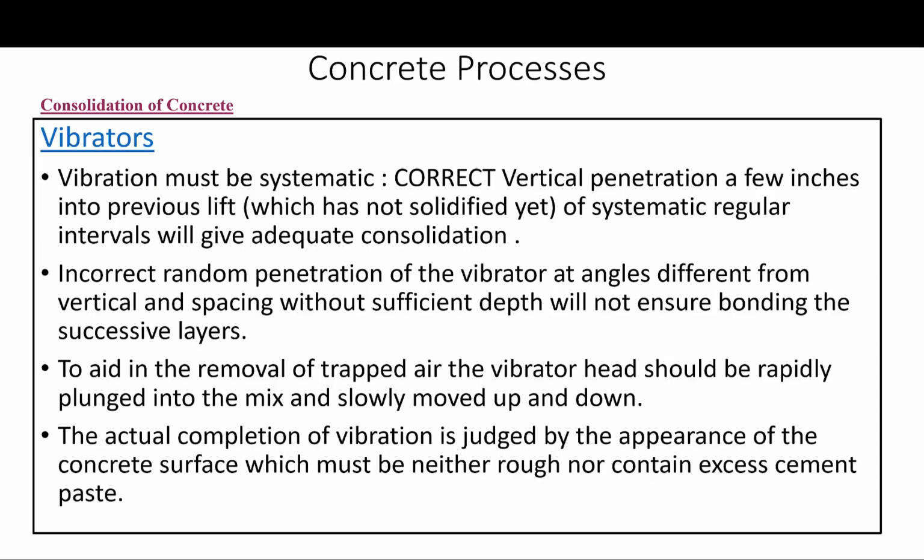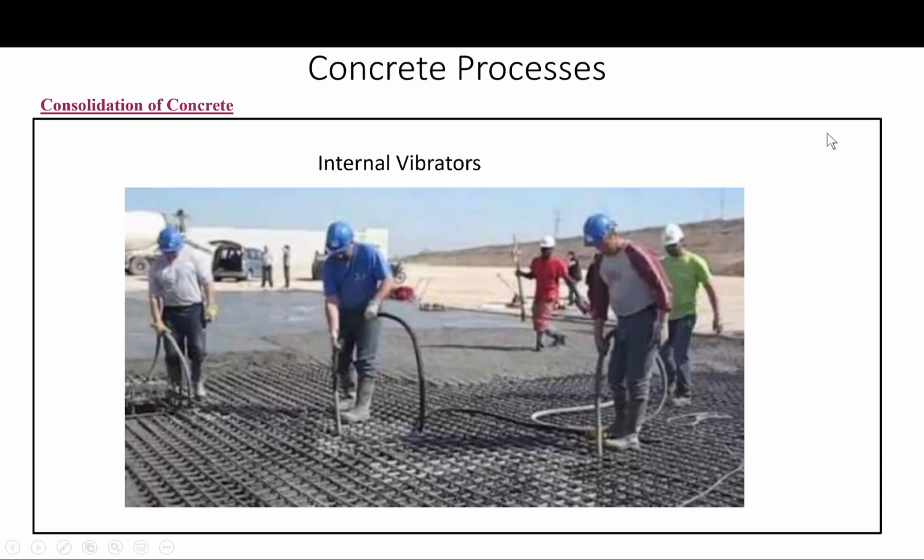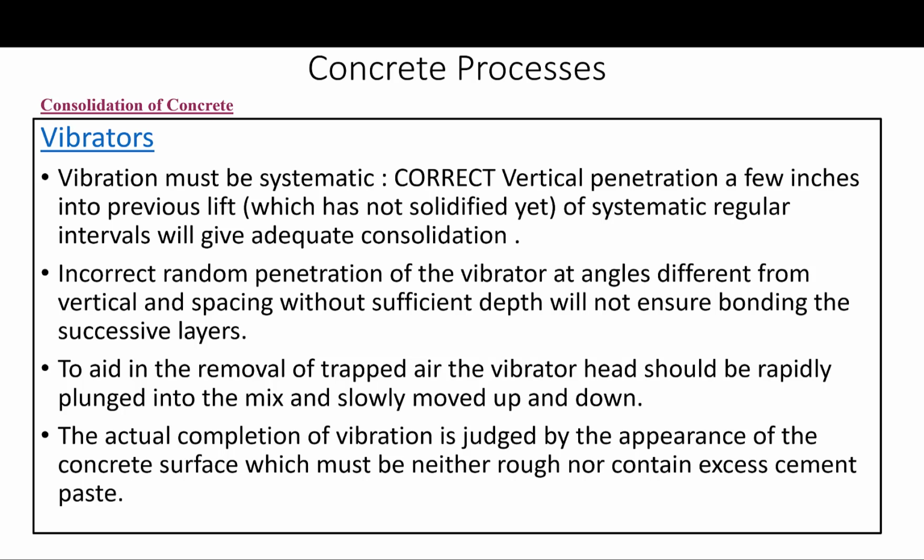Okay, so about vibrators. This photo shows you the concrete workers here using vibrators. So let me talk more about vibrators. The vibration must be systematic. Correct vertical penetration, a few inches into the previous lift, which has not solidified yet. Otherwise, it defeats the purpose. This is of systematic, regular intervals. This will give adequate consolidation.